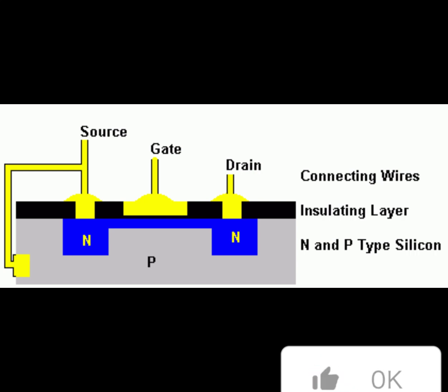When we apply positive gate voltages, the holes present under the oxide layer experience a repulsive force, and holes are pushed downward with the substrate. The depletion region is populated by the bound negative charges that are associated with the acceptor atoms. The electrons reach and the channel is formed. The positive voltage also attracts electrons from the N-positive source and drain regions into the channel.